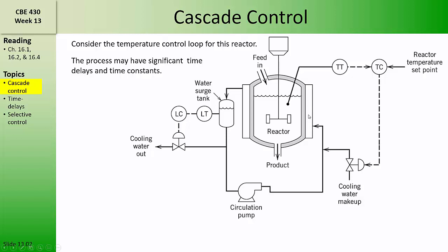water to the jacket, and then from the jacket across this thermal boundary representing the reactor wall to the contents of the reactor. The residence time for the water in the circulation loop represented by the cooling jacket and the residence time for the process fluid flowing through the reactor are time constants that will both appear in the feedback control loop. Additionally, there are time constants associated with the heat transfer.